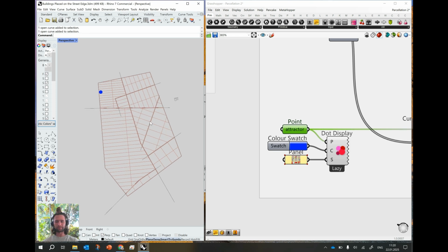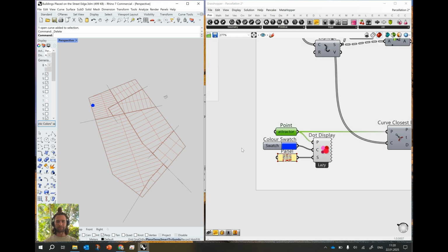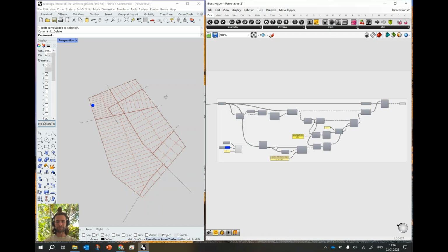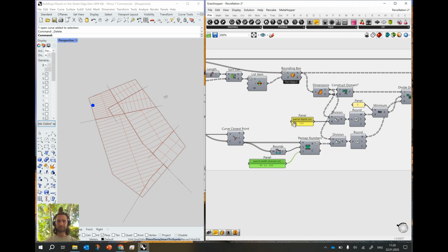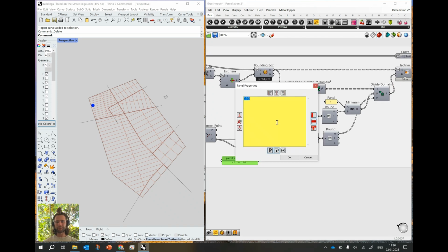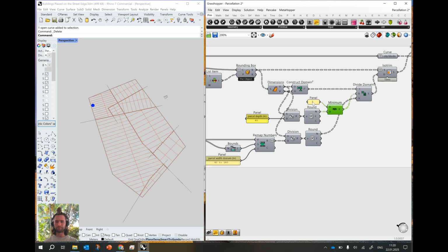Imagine that we have the street network which is not dense enough to generate parcels, like the case we have here. So now we clearly see that most of the parcels have a bad shape, and it would be quite hard to fix it just by changing those two input parameters, simply because the parcel depth cannot be manipulated anymore, since we have this capping 2 here.